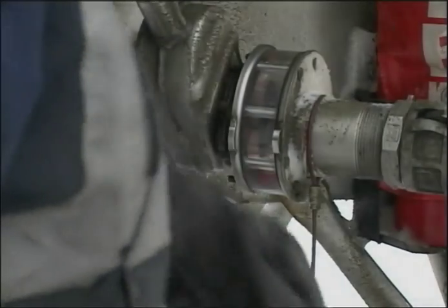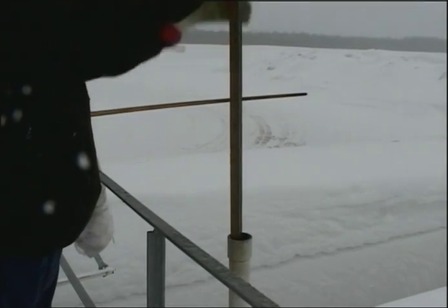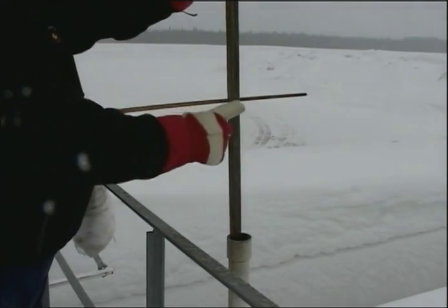When all the fuel has been pumped into the tank, wait at least 5 minutes for the fuel to stabilize. Then, re-dip tank and record findings.